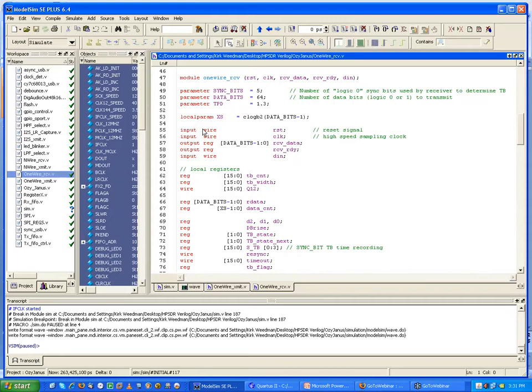And in the newer standard of Verilog, there's a Verilog 1995 standard, there's a newer 2001 standard, and in the newer standard you're allowed to just put the wires or regs right here on the same line as the input and output. Typically before, you would put them separately, you'd just say input reset, and then you'd have wire reset on a separate line. But you can do that all in one line now. And I'll show you that in the compiler options in the actual Altera tool today, if you remind me if I don't forget.